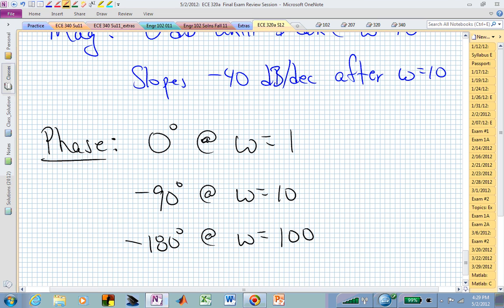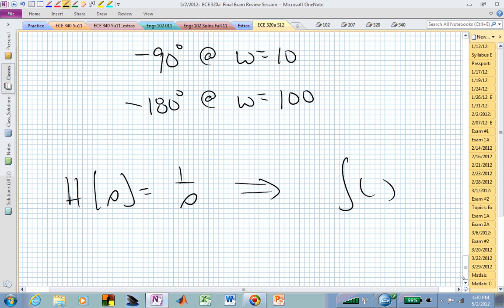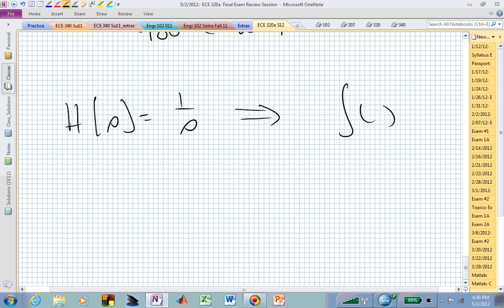So now let's look at a pole. I think the question was, how do we reason this magnitude behavior in terms of this always-on behavior of a 0 or a pole at the origin? If we looked at a system H(s) which is 1 over s, as an operator in the time domain, that's an integrator. And so if you looked at an integrator, what's that doing at low frequencies? It's really building up and up and up dramatically at slowly varying frequencies, at low frequencies. You have 1 over s that now looks like an integrator in the time domain.